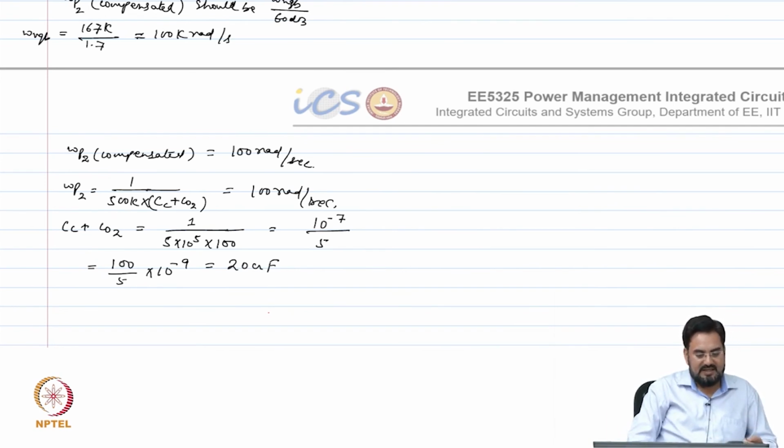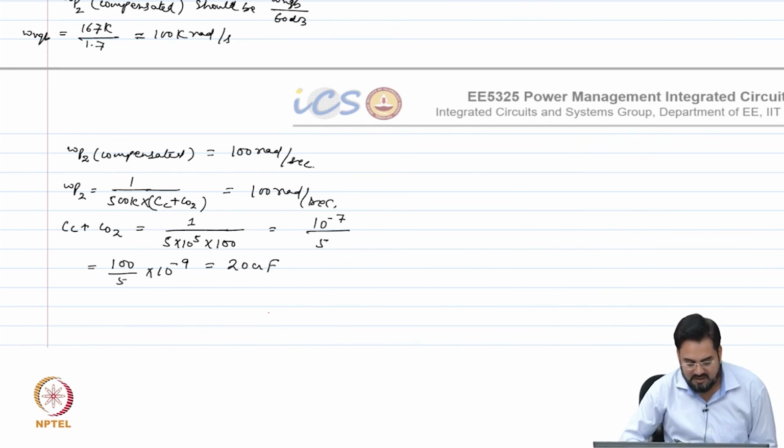So, we will take the case where your capacitor requirement will be of the order of maybe hundreds of picofarad, or maybe maximum 1 nanofarad, and then we will see how we can reduce that cap with the Miller compensation. Okay. Then after that there are some more compensation techniques, we will talk about that as well. Okay.